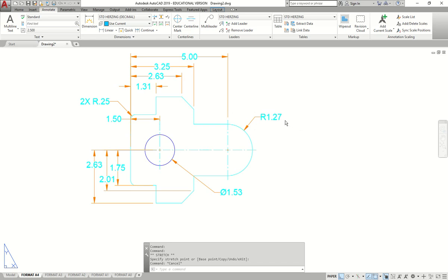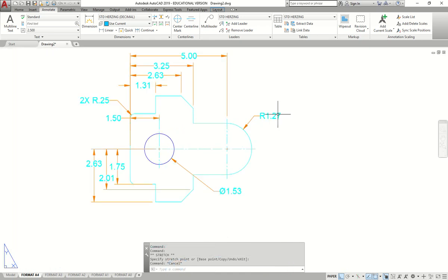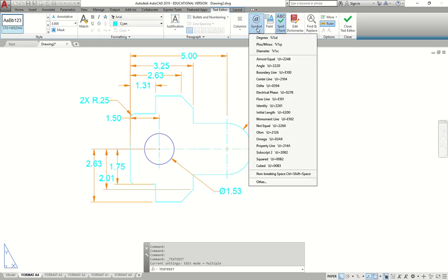We don't have to do it, but let's pretend like we need to do it. All you need to do is, again, double click on the actual annotation. Click inside. We don't erase the actual dimension. And you could go to symbols. In here, you could load multiple different symbols that you need. Once we start doing the mechanical later on, you're going to need some mechanical symbols.